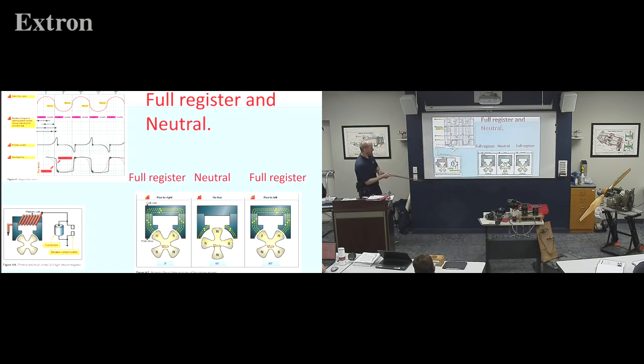So when the amp draws the highest, I open the contacts and I get this huge change in flux field that collapses across my secondary coil and just makes a tremendously huge voltage that wants to jump across the air gap in the spark plug. So that's how we actually make spark: it's not the electricity going through that makes the spark.